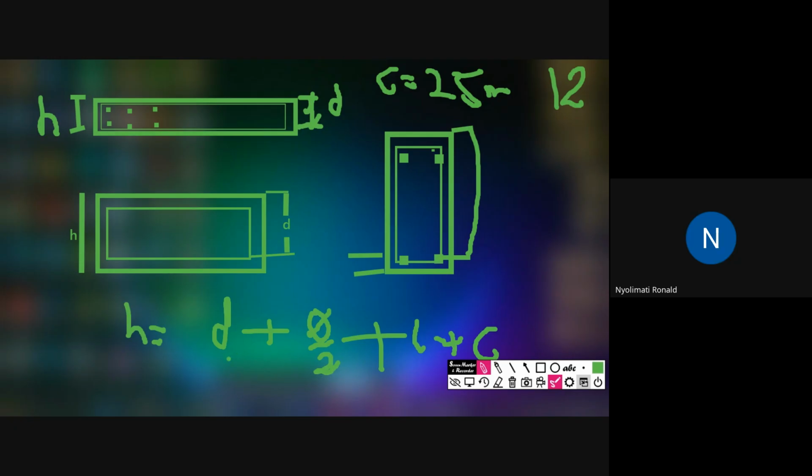And now we have calculated our D as 153.8, which is from here up to the midpoint of this bar. We don't have the remaining from the midpoint of the bar up to here, but we can get the remaining for the bar, then the whole of the link, then the cover. Let me say we are using a link size of 8 millimeters. So let's start calculating.